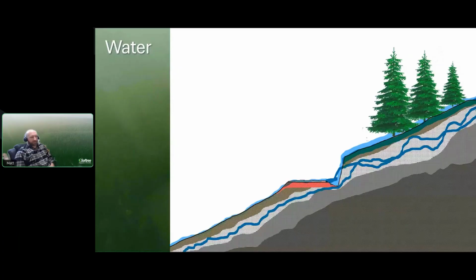If we do things well, we have a cross drain to convey water across the road at a preferred location. If we don't, or the water can't get to the desired location, well, maybe we have spots where water travels a little ways down the road and then ponds and overtops the road. So it ponds at a low point and goes where we may not have intended it.